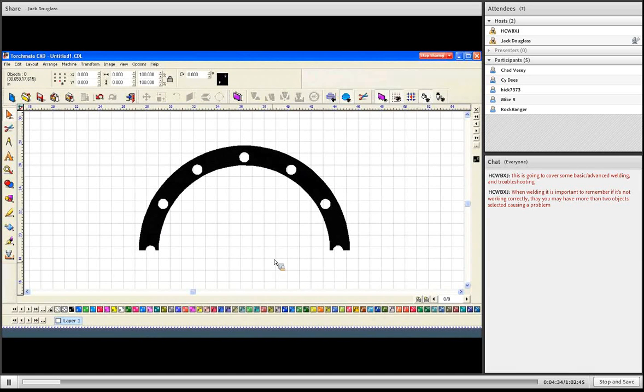At this point this part's done, but what I'd also like to show you is how you would draw a part like this. There are a few ways it could be drawn. Probably the easiest is to draw it as a few circles, then array the circles around the outside and cut in half. So we'll start out. It looks like the height of this was about 9 inches, and inside we'll call it an inch and a half or 2 inches, and then the circles about 1 inch.